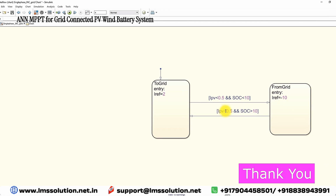If IPV is greater than 0.5 and the SOC of the battery is greater than 10%, then we can send some power to the grid. That's why we are sending some power to the grid with a peak amplitude of 2 amps current.